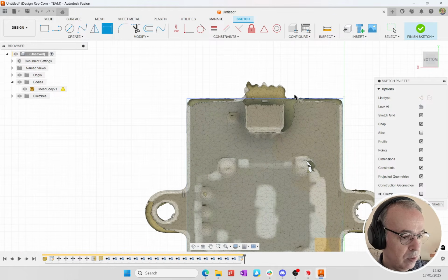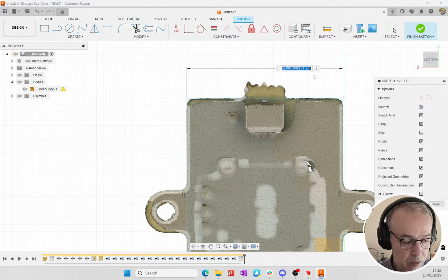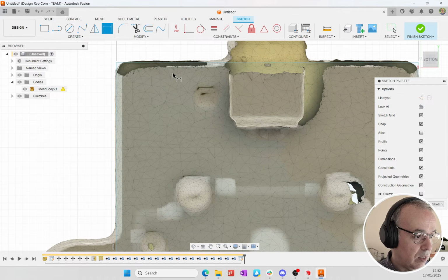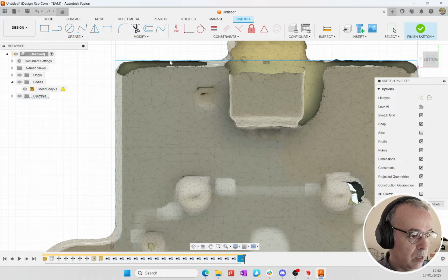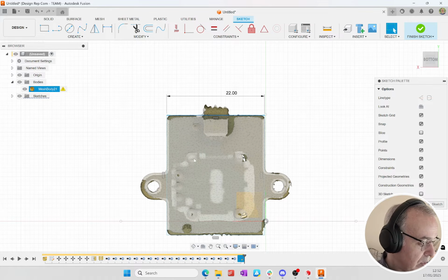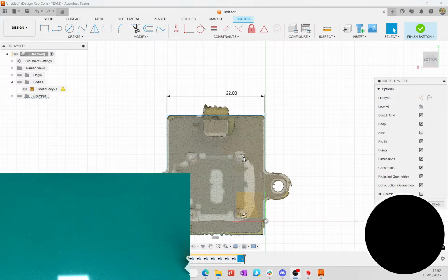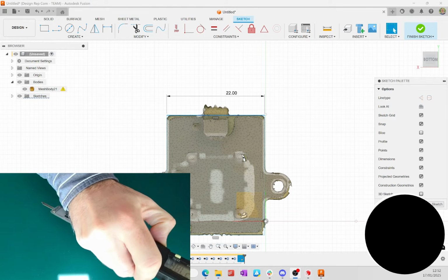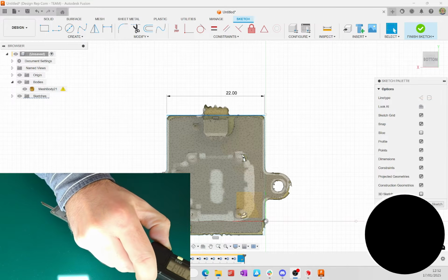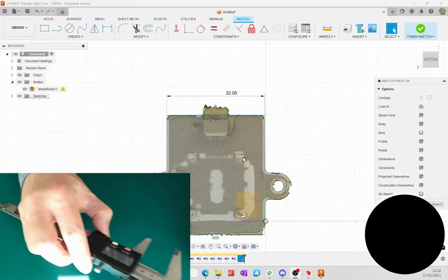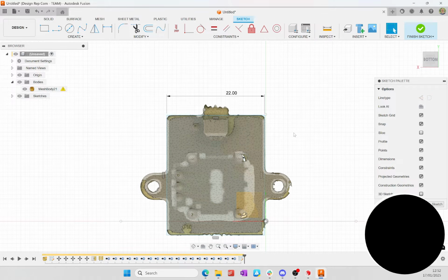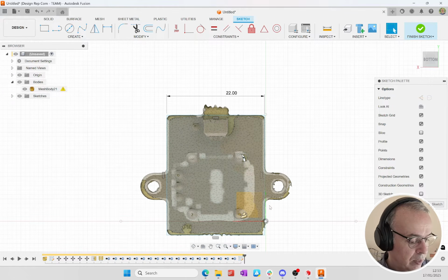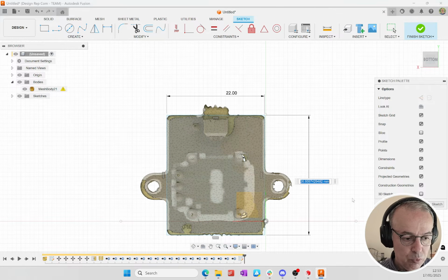Recalling our earlier measurement, the width is about 22 millimeters. I won't enter 22.084 millimeters, just 22 millimeters, which will establish the foundation for constructing the piece. In this situation, I can also check the total length, which is about 27 millimeters. I'll dimension this area and set it to 27 millimeters, which is nearly the exact value.